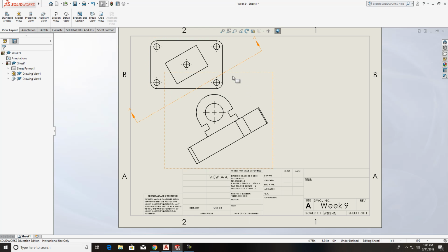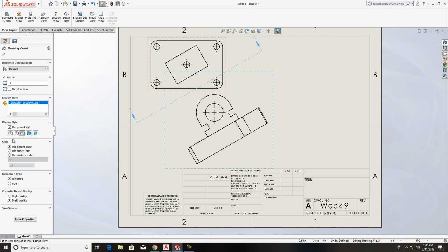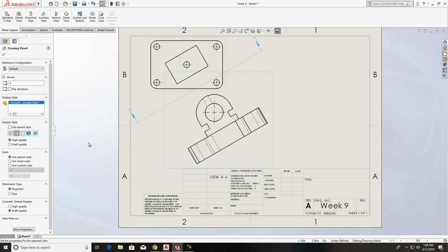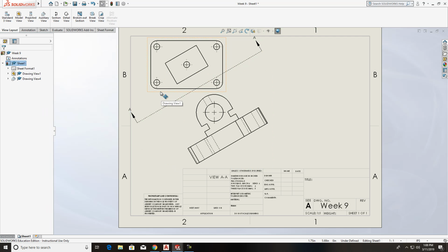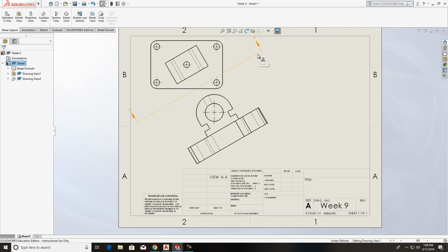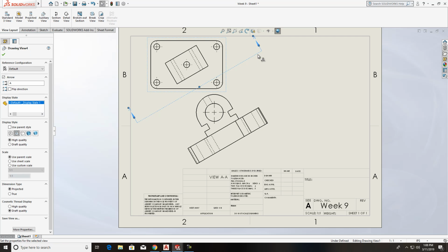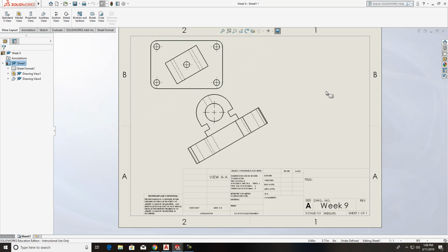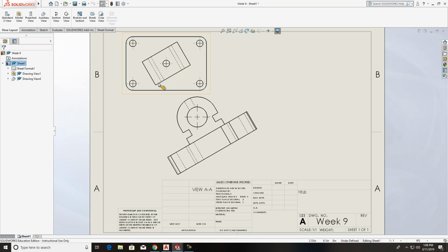And I want to take and click, because we need hidden lines on these. So when you come over here, just make sure that you have your hidden lines turned on. And make sure, usually when you come up here and do this as the parent view, that everything follows that. Good. And I want to turn the arrow off right there. You see that. There's no sense of having that because everyone knows that's where that's coming off of. So just get in there and do this project.